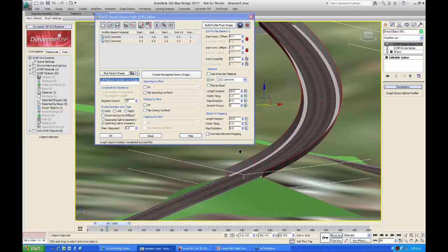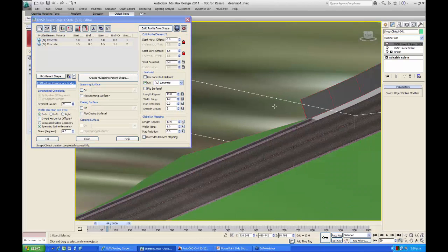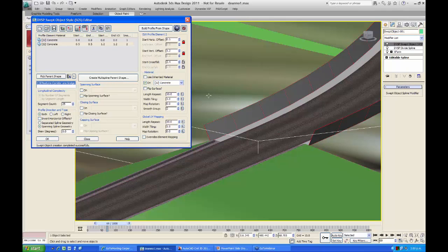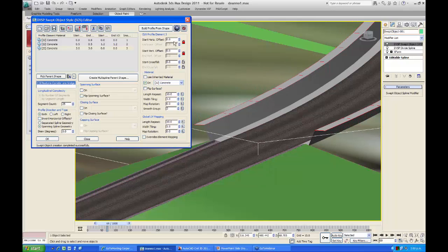I'm going to have a look at what we're actually doing here in the background. So you can see we're constructing elements for the shape of the bridge. Bump it down to 1.4, 1.2 meters high, say. Make another one. Let's go out horizontally for, say, 300 mils. You can type in there if you want, 0.3. Let's go another element.